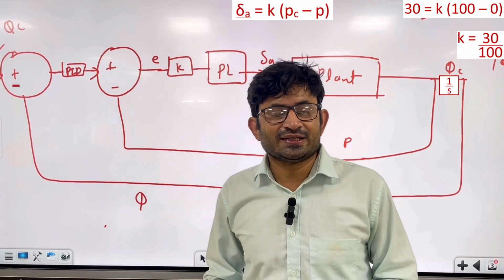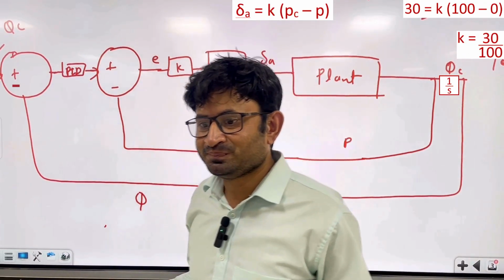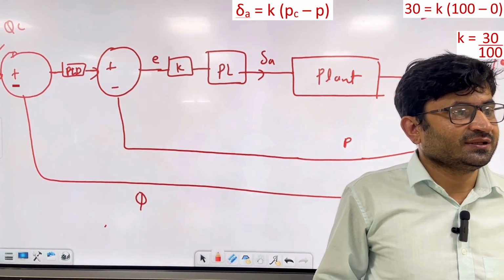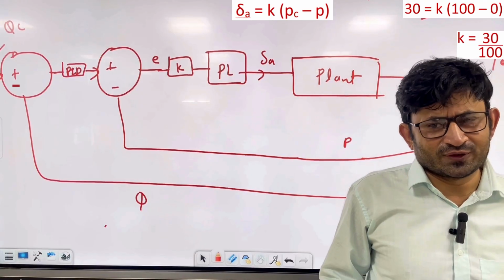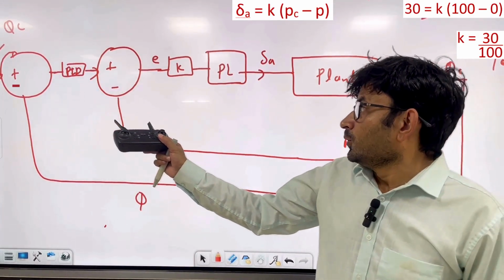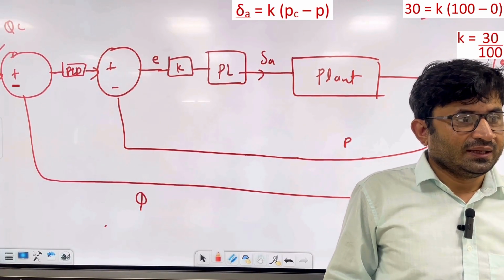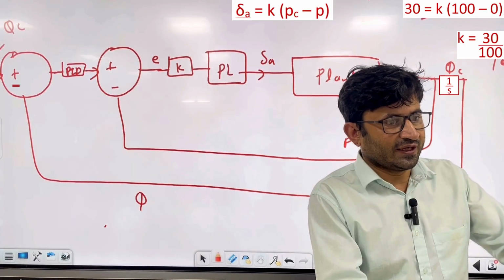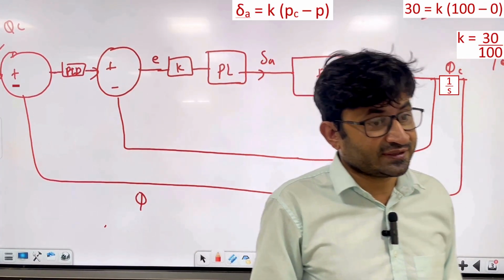In this case, when the pilot releases the stick, naturally the aircraft will come back to some kind of stabilized mode, right? So that means here what is phi in stabilization? 0, right? Level, right? In that sense we are talking about stabilization. Similarly for the pitch case, when you release the stick, the flight becomes level. For example, let's say this is the aircraft. The flight was this. When you release the stick, the flight naturally becomes level. That is the beauty of stabilization mode.